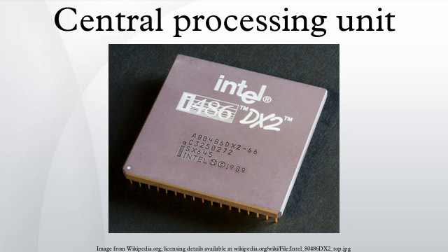Most of the difficulty in the design of a superscalar CPU architecture lies in creating an effective dispatcher. The dispatcher needs to be able to quickly and correctly determine whether instructions can be executed in parallel, as well as dispatch them in such a way as to keep as many execution units busy as possible. This requires that the instruction pipeline is filled as often as possible and gives rise to the need in superscalar architectures for significant amounts of CPU cache. It also makes hazard-avoiding techniques like branch prediction, speculative execution, and out-of-order execution crucial to maintaining high levels of performance.